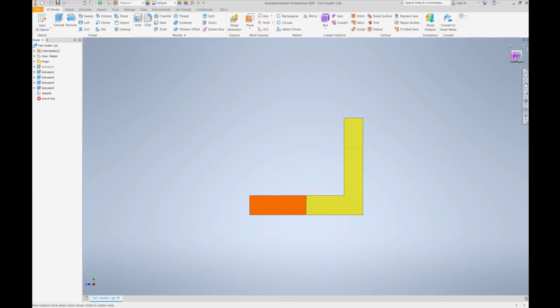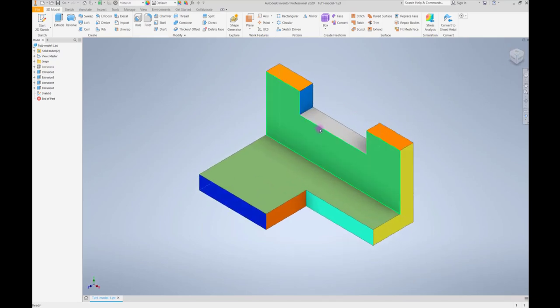So this hidden line represents that there is a surface that I cannot see from the right side view. And for this surface, we will need to make use of a hidden line to denote the position of the bottommost part of the surface.